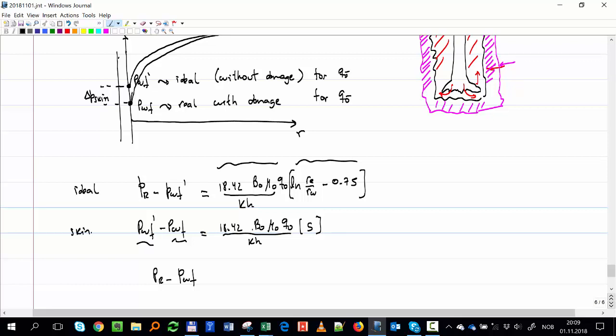And then I say, well, that delta P, I'm going to express it as this number times a dimensionless factor called S. We will see now why this is a bit confusing, but why are we doing that? Basically, the idea is to make the pressure drop dimensionless. I make it dimensionless by taking this constant and putting it in front of this S. When I sum up both equations, I end up with the following: